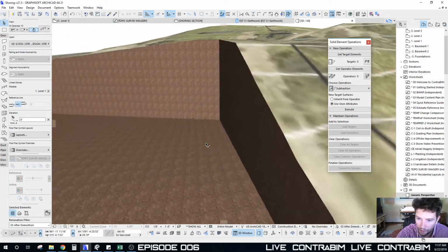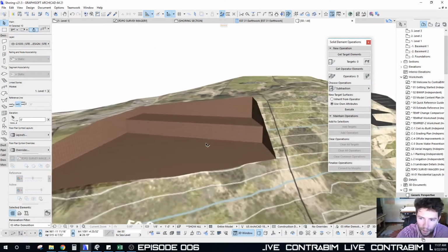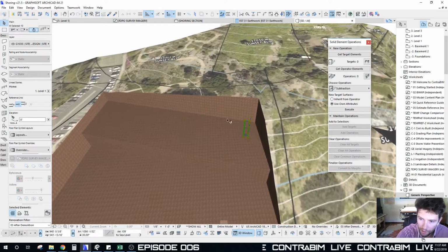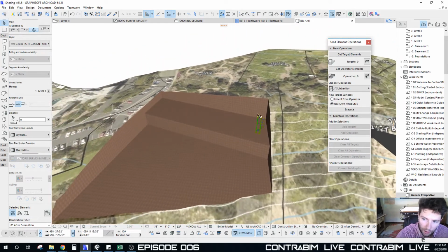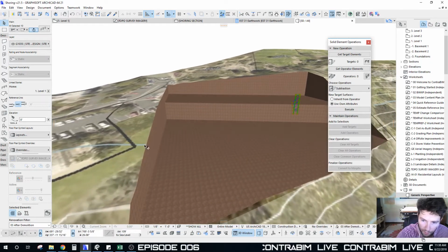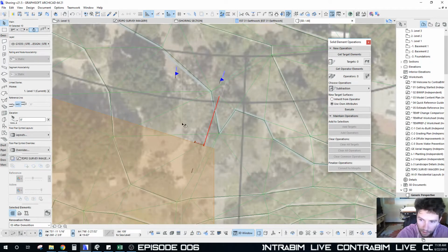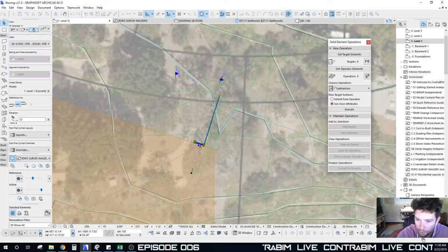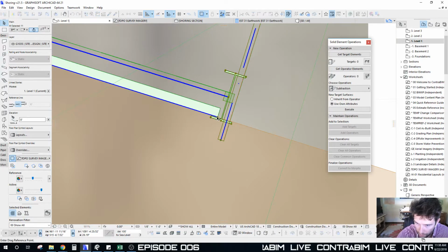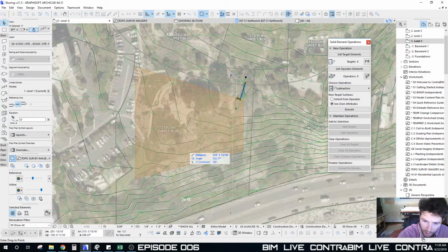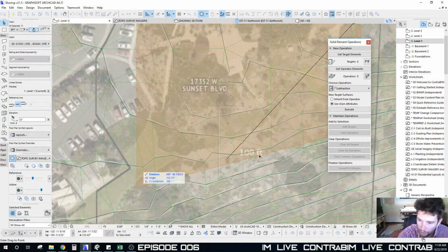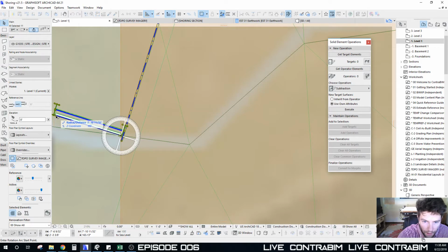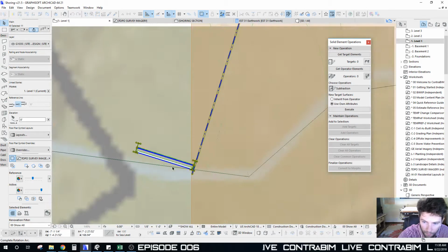So again, maybe this wasn't the best place to start with this shoring, because this was set up essentially on our first floor going down. So it's essentially from this point going down. So maybe we should start it where we have our right elevation. Would probably be a little smarter on my part. So let's just take this over, and we're going to find where our 100 hits our edge of our shoring.